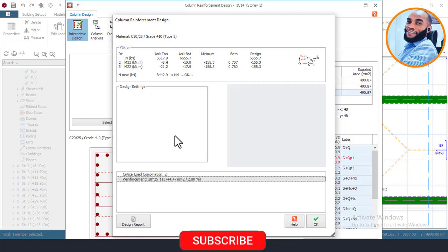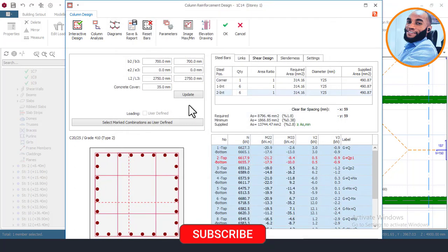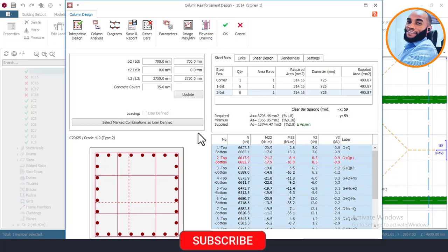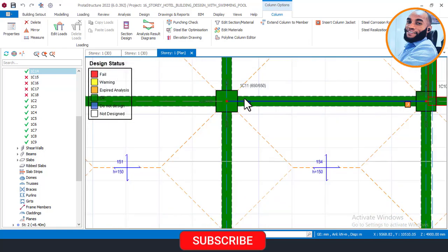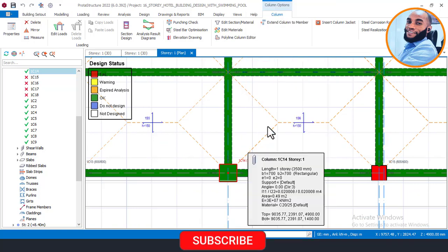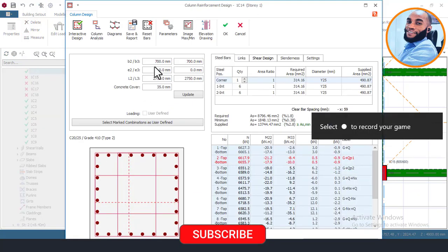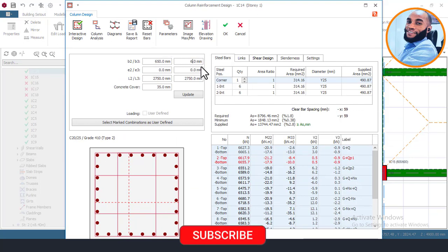Although it is safer, it is cheaper to increase the size of the concrete section than to use more number of bars. It is cheaper for the client to afford concrete than to afford steel. Okay, so I can use 700 for that, and then say okay and then okay. So when you're designing, also put into consideration the cost of the structure. But just to maintain the 650, the same column size, so that I will not spend much time during detailing. So always try to use few column sizes that will be grouped together, so that you don't have more column types.